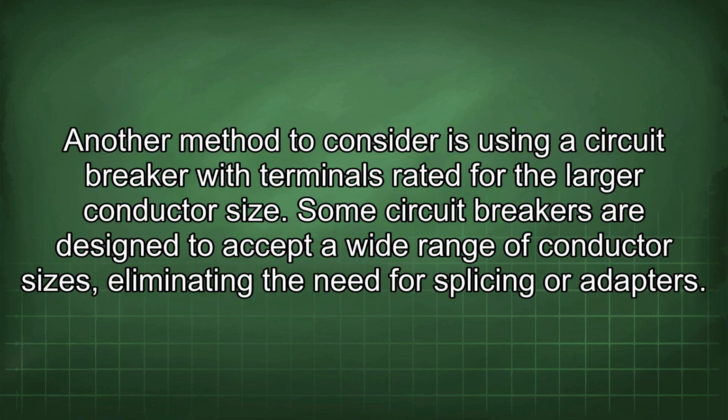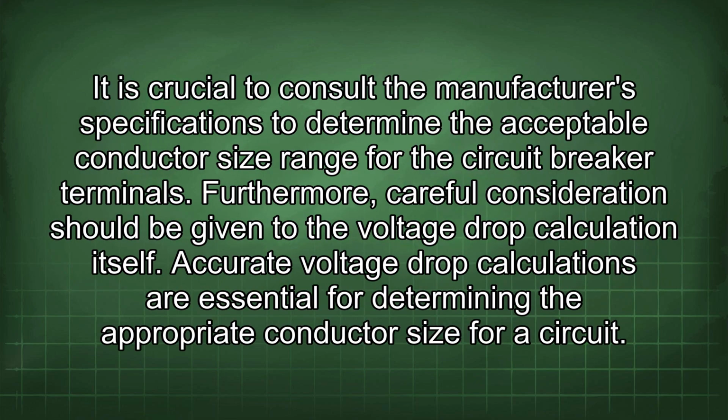Another method to consider is using a circuit breaker with terminals rated for the larger conductor size. Some circuit breakers are designed to accept a wide range of conductor sizes, eliminating the need for splicing or adapters. It is crucial to consult the manufacturer's specifications to determine the acceptable conductor size range for the circuit breaker terminals.